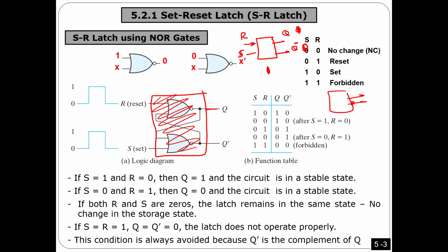Okay, guys. Anyway, here I'm going to explain how this one works. But for now you should understand we have what we call SR latch. It has 2 outputs. It's actually one output, but one output is the stored value and the other is the complement of the stored value. And we have 2 inputs here. The purpose of these 2 inputs is to control the stored value, or to change the stored value.